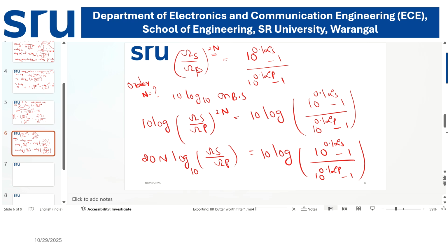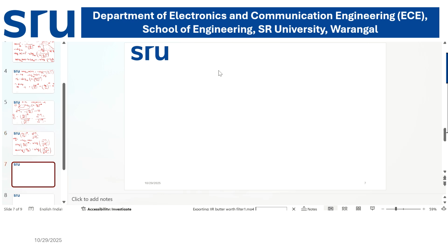Now 10 here, 20 here, the 10 will get cancelled. Therefore we have 2n log base 10 of omega s by omega p is equal to log base 10 of the numerator value.